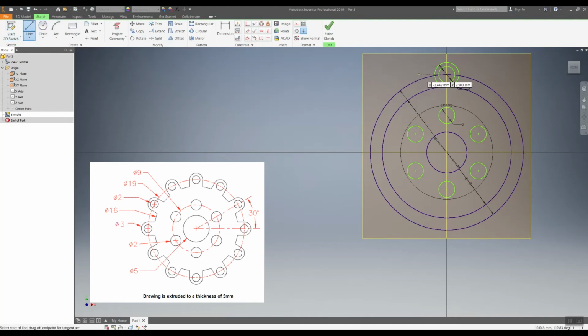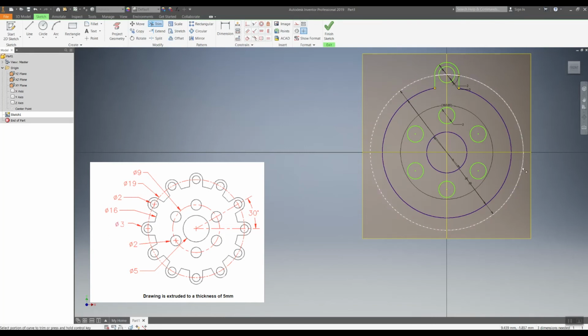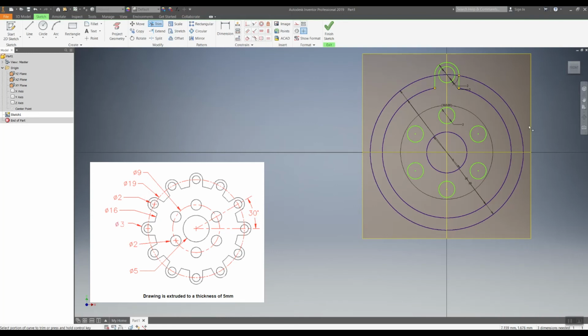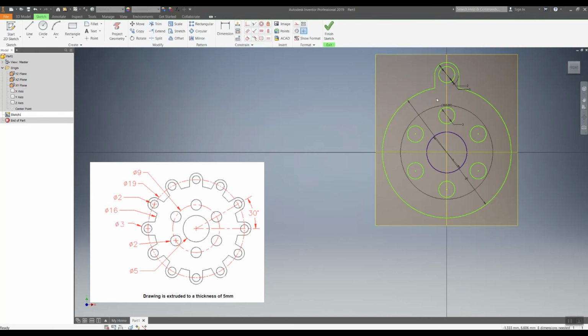And if I take some lines and go straight down, take my trim command, and create an object that looks like this, I think I can rotate that around and get the same look. Let's give that a try. First thing I want to do is erase this outside line here though. And we can just spin this around this inside. We're going to have to keep this inside line because we need to cut away this part right here.